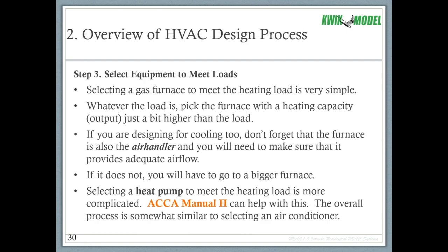But don't forget that your furnace is your air handler for your air conditioning system. So another very important part of selecting a furnace is not just meeting the heating load, but making sure that it provides enough airflow to handle your cooling load as well. If your furnace does not have enough airflow, you may have to pick a bigger furnace than what you need for your heating load. You might actually have to oversize your furnace.